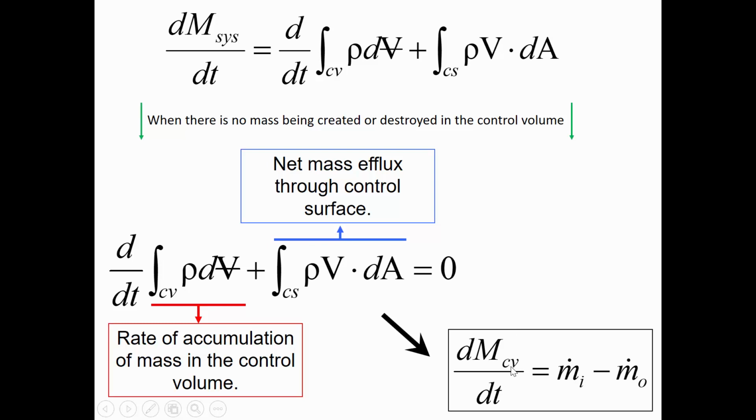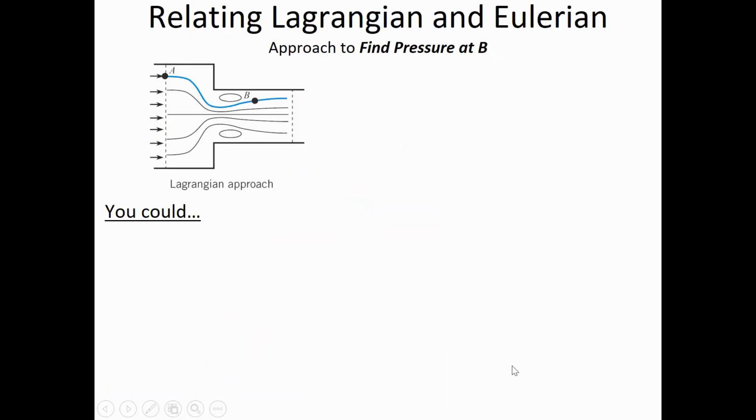So this is the Reynolds transport theorem, and it can be applied in a lot of ways. One of the ways we can use it is to use formulas that apply for conditions along a streamline. Remember, we've emphasized several times that Bernoulli's equation should be applied for an inviscid fluid that's incompressible, steady flow. But one of the assumptions is that it's along a streamline. The Lagrangian approach says that you need to track the trajectory of every particle in your system if you want a full and complete understanding of all of the velocities and pressure changes. This Lagrangian approach says let's keep track of streamlines.